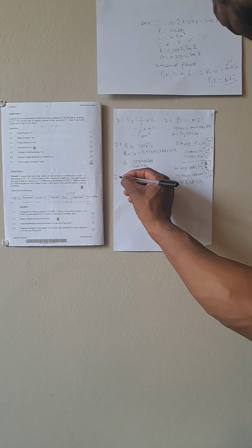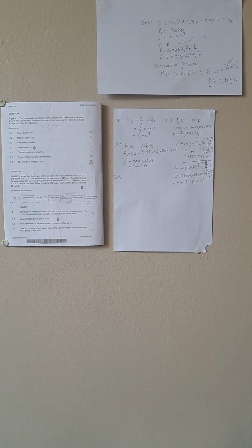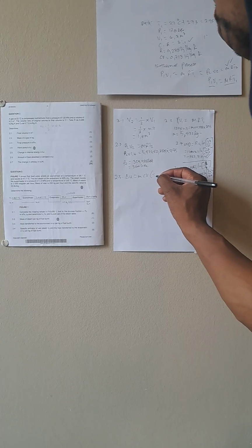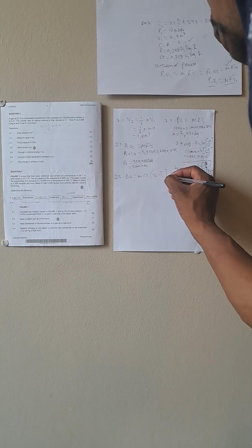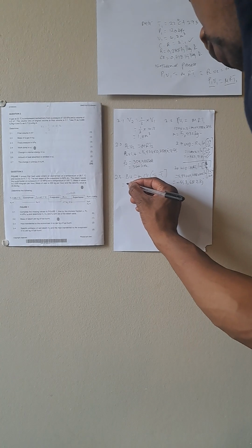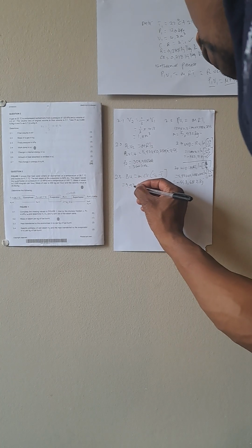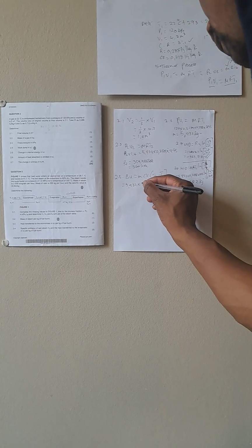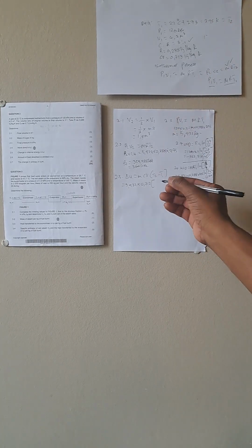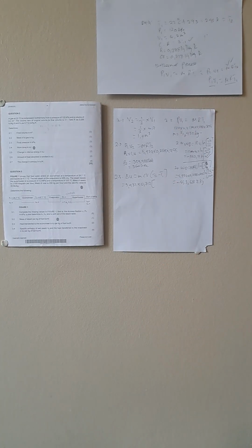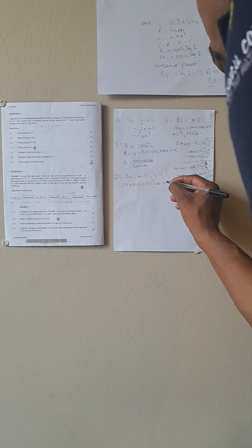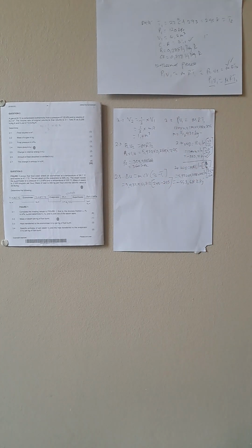Let's go to 2.5. We need to calculate our change in internal energy, delta U equals MCV into T2 minus T1. We are just substituting because we already have everything at our disposal. So we have our mass 5.932, our CV, which is 0.712, our T2, we say it is 295 minus 295. Remember, it's an isothermal process.